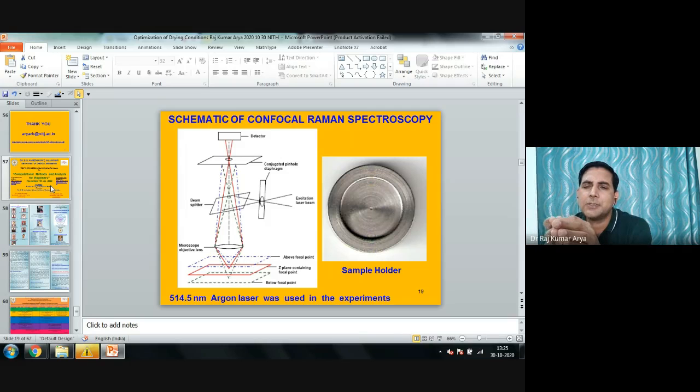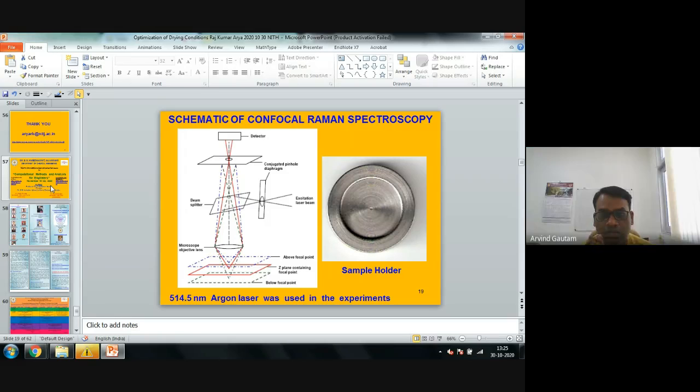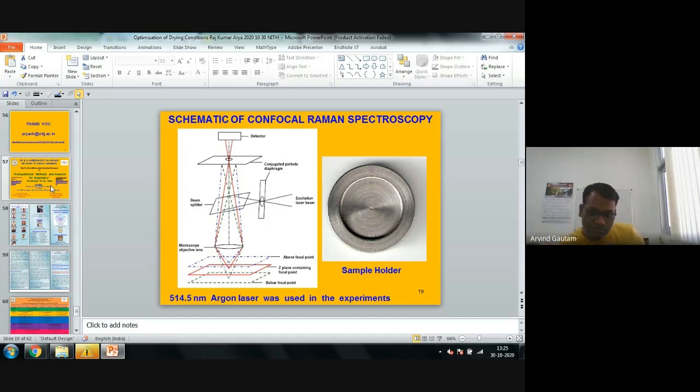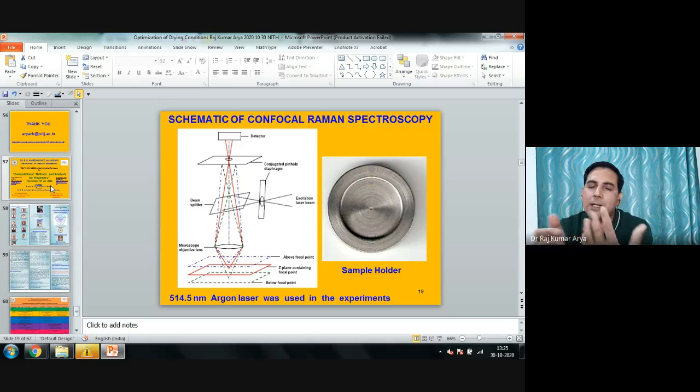Yeah, you have. If you want the interaction in terms of bonding or strength, how rigid it is, how it can be peeled out, you have a peeling instrument. You can put a press on the film, just like a vacuum pump sticking to the film, and try to take it out. You measure the peeling force, how much force you have to put to peel it off. Those instruments are there.